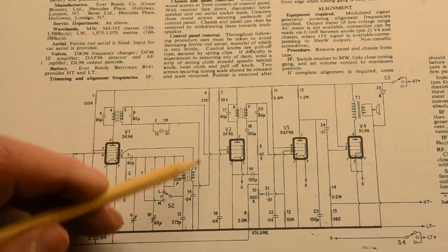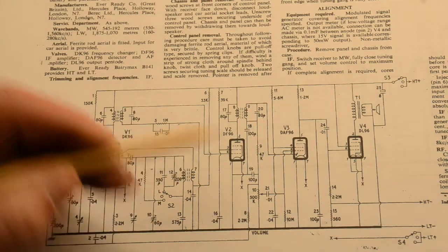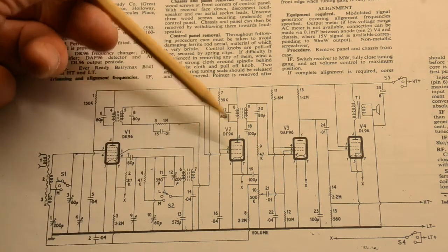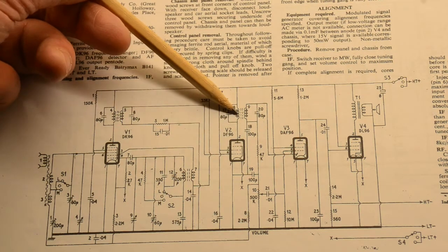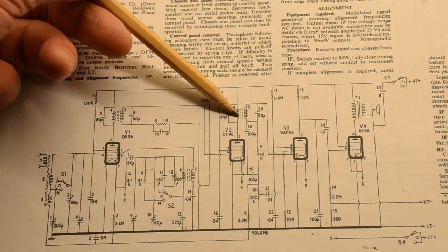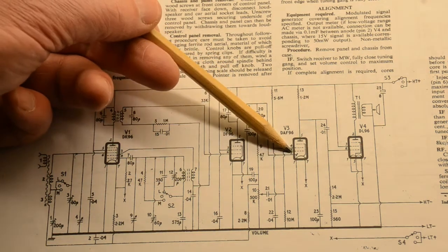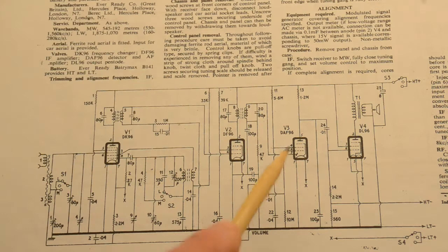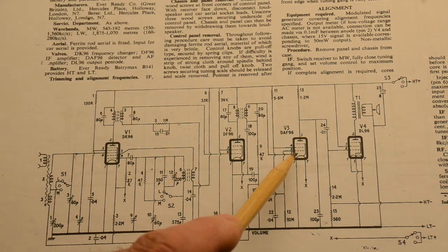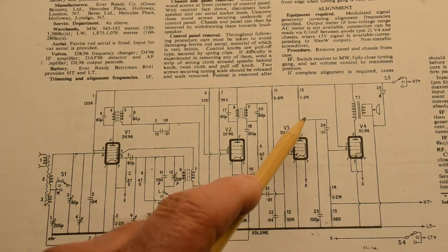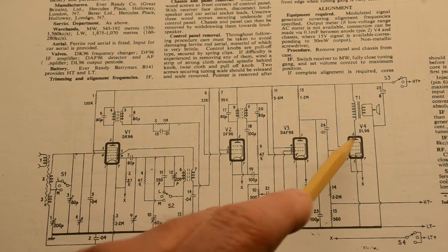The IF passes this through, modulated obviously by the signal coming through, and goes into the 2nd valve. This is our only IF amplifier, amplifying that frequency through the IF transformer, 465, 470 kilohertz, and it comes out the other end, fed into the diode of the diode pentode, note the diode at the bottom. Then once it's gone through the diode, it's been rectified, and we come out the other end and we can feed it to the output stage as an audio frequency signal.